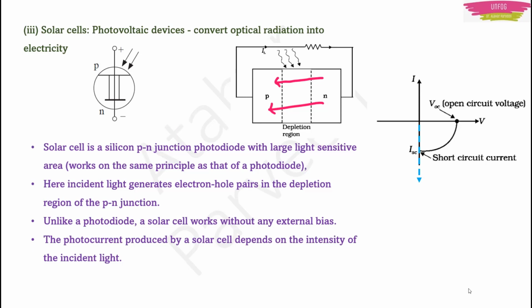Okay. So this is a typical IV graph for a solar cell and it is very much different from other diodes, especially the PN junction diode. So you have to remember this graph also. They may give this graph and then say that it resembles an LED, solar cell, photodiode or a PN junction diode. You should note that this is a solar cell graph.